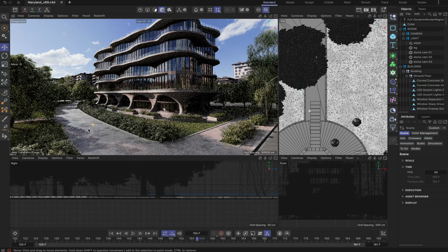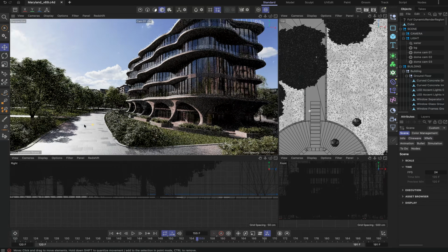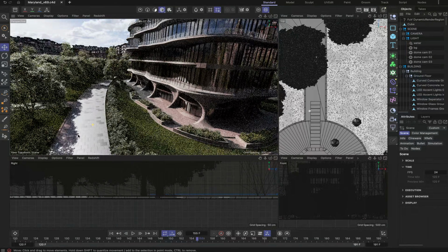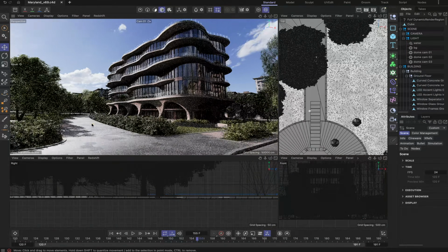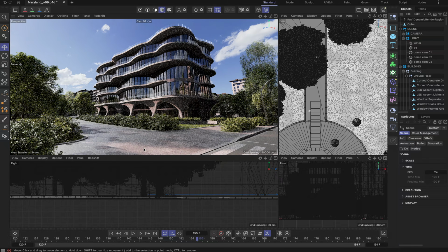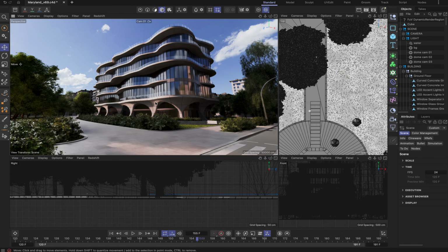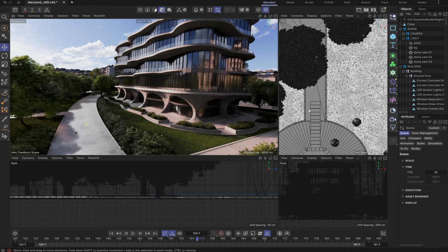This is Redshift Live, Maxon's modern real-time path tracer, rendering one of their high-quality 3D assets in Cinema 4D on Apple Silicon. You get all the benefits of path tracing in the viewport, but during camera movement, you can see some noise from the 1 sample per pixel presentation. Enable the MetalFX Denoiser, and the image becomes dramatically more stable and noise-free.